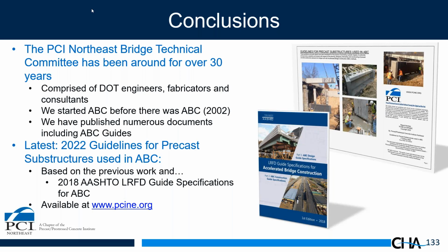The reality is, in most cases, the deck that's cast on top of those beams is typically standard state DOT deck concrete. So the durability of that concrete should be equal to any cast in place deck out there. The closure joint materials, there's different materials being used. Ultra high performance concrete has been used, and high early strength concrete has been used. And our experience to date is those mixes tend to be even more durable than normal deck concrete because they typically are very high strength, which usually results in very low permeability.